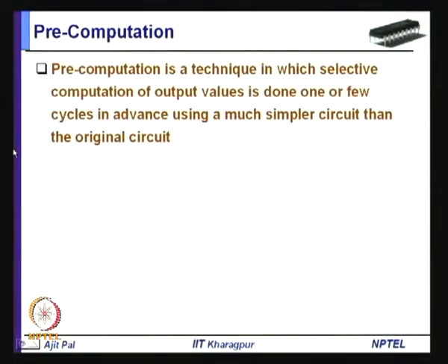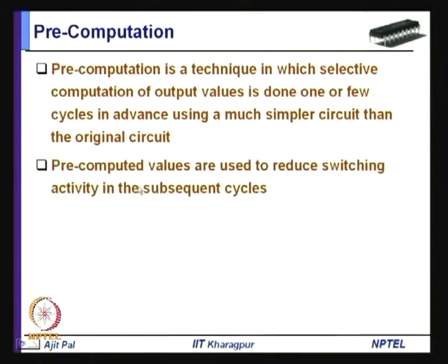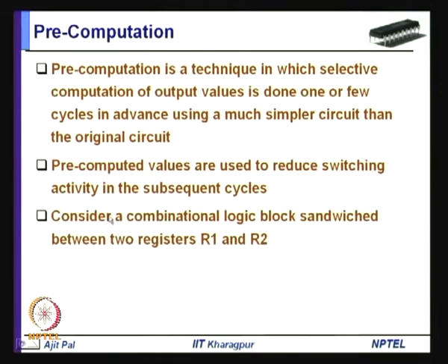So, you will identify some simpler hardware which will do some pre-computation a little in advance, and then you will use these pre-computed values to reduce switching activity in subsequent cycles. That is the basic idea of pre-computation, and it is done by a simpler circuit, as I have told.